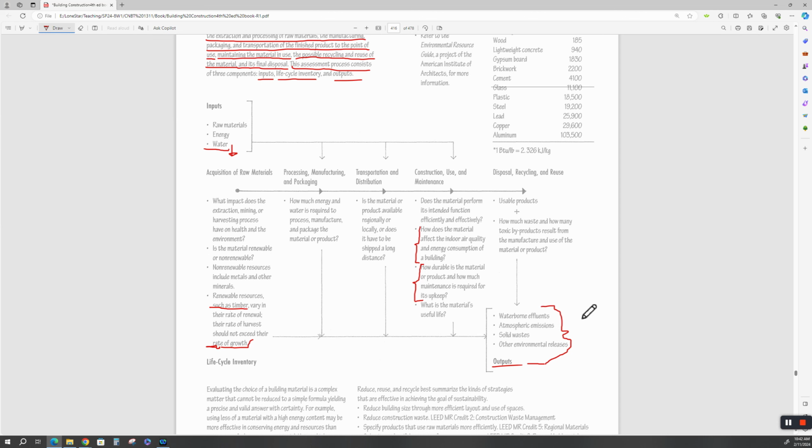I know a contractor up on Lake Belton not too long ago needed to re-side or put new siding on a house. And he got there and he found out this was some cement asbestos siding. And they were like, oh God, what are we going to do now? So they put furring strips over that siding in alignment with the studs behind it, and then covered it with Hardie plank. They encapsulated it so they didn't have to dispose of it.